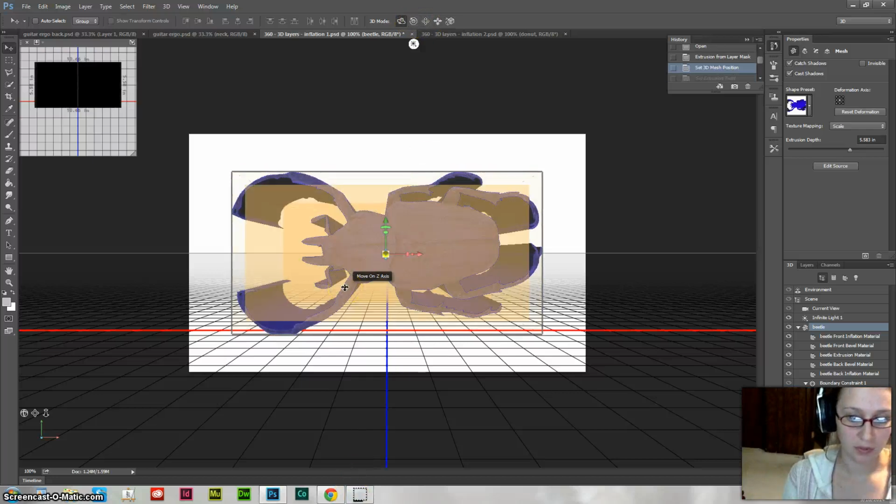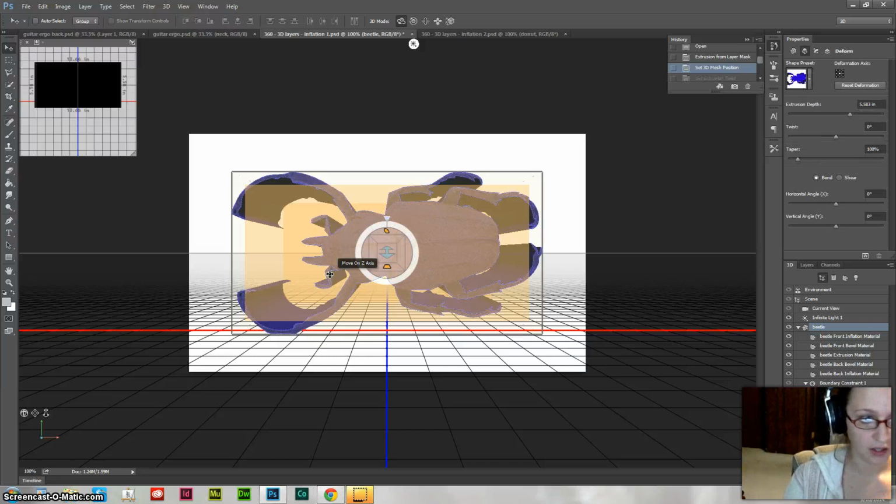We will now be using something called the HUD, Heads-Up Display, which is a hands-on innovative system to modify the model by clicking and dragging directly on them. You're going to click directly on your object with the Move tool so that the 3D model, rather than the whole scene, is active. It will also have a yellow box around it as shown. Press V to access the heads-up display.